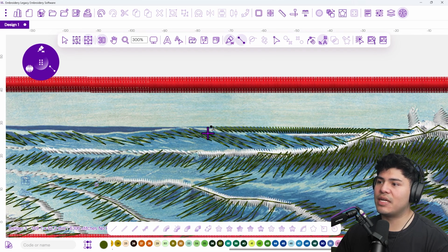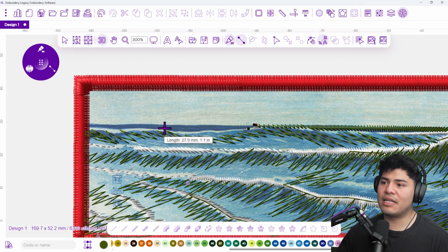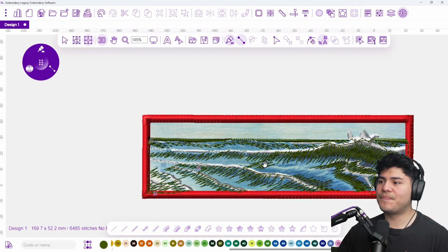And I'm going to press enter, left click, left click, left click, and left click, just to create this little shape or this little detail. And then the last one, left click to create point, counterpoint. And I'm just creating these widths all around 1.4 millimeters. Perfect. And I can press enter all the way back there.